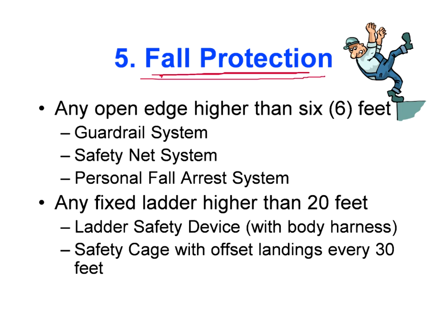And the last one, with this we complete this class. It's about fall protection: how to protect a man from falling from a workplace. Any open edge higher than 6 feet is dangerous. Any open edge higher than 6 feet, you have to protect it. Below 6 feet doesn't matter. If it is more than 6 feet, we have to give a safety system.